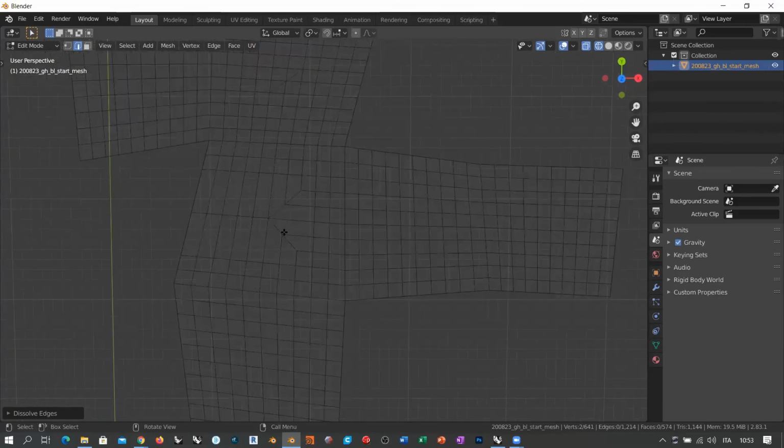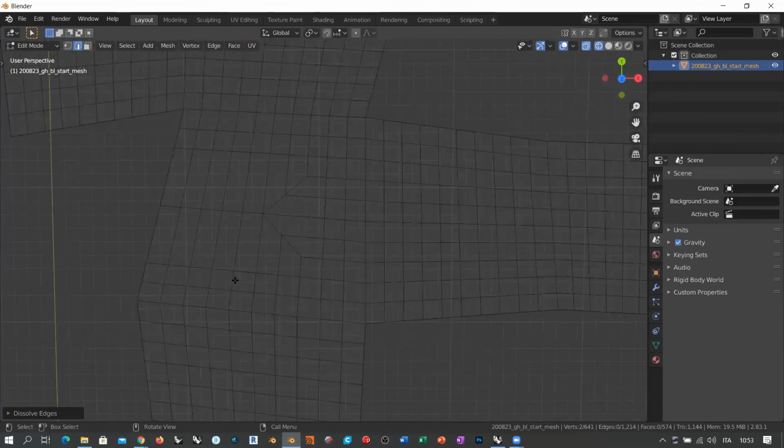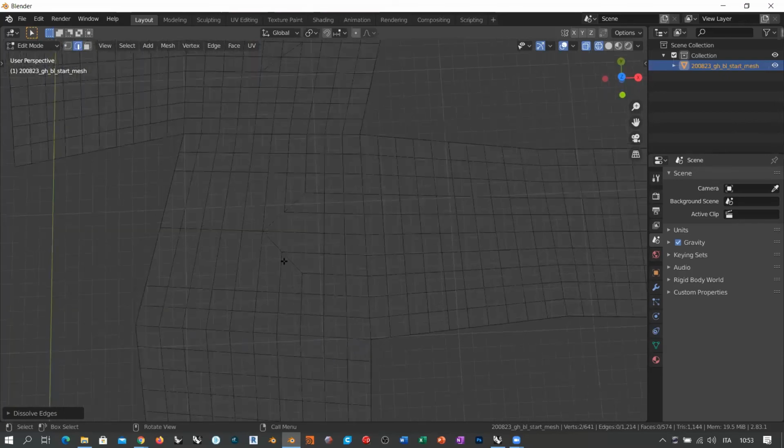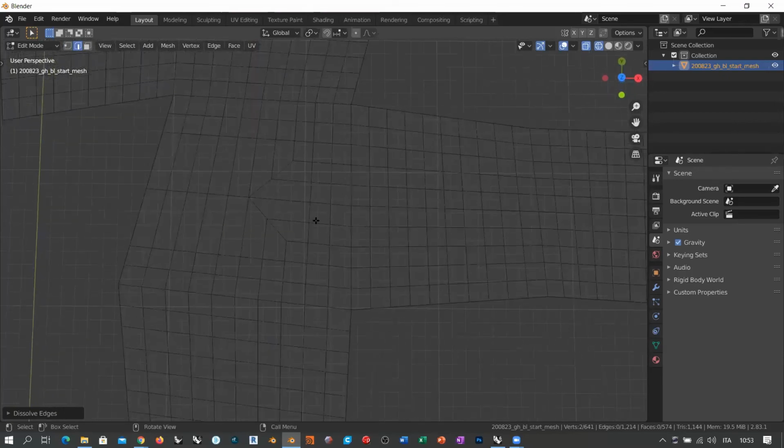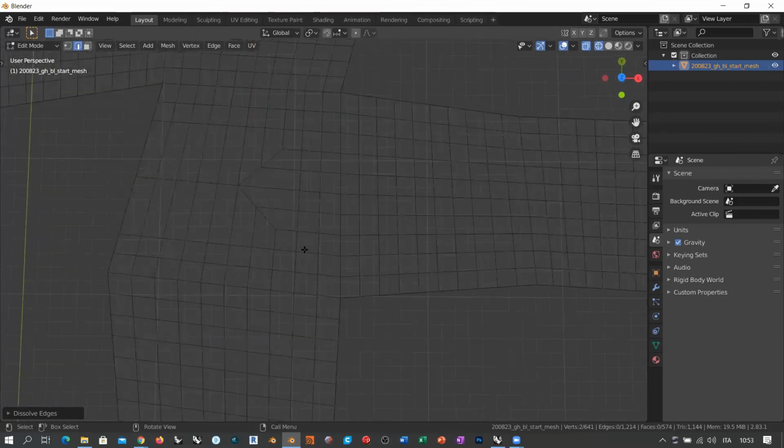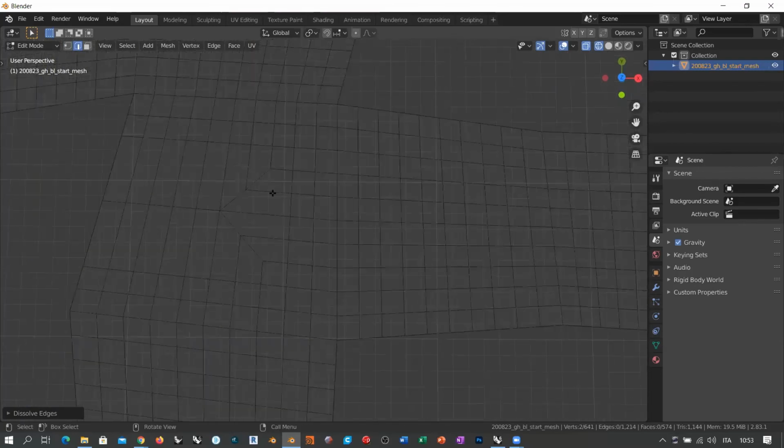Okay, so it's evident that this operation is also simplifying the topology because we are getting rid of many edges. But nevertheless, let's work on the main topology and then we will see what happens. Once again, I have to reach down to these corners here. So the operation is always the same. So vertex selection, add an edge, add an edge here, and then edge selection and start dissolving the triangle. So these and these must go away, these and these must go away, and everything that depends on them.